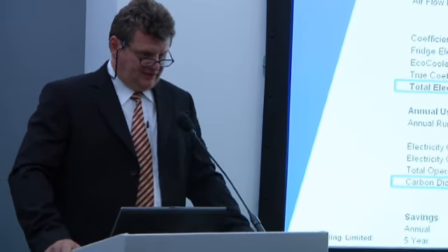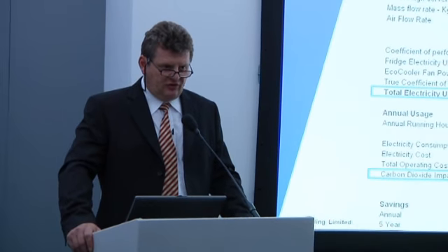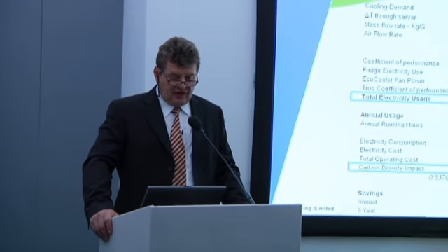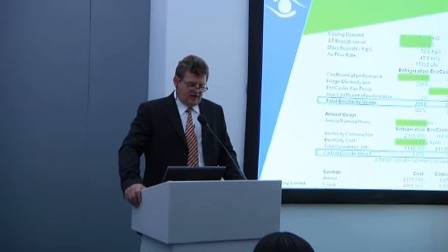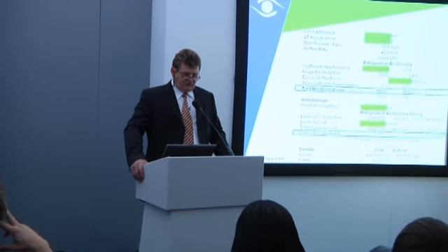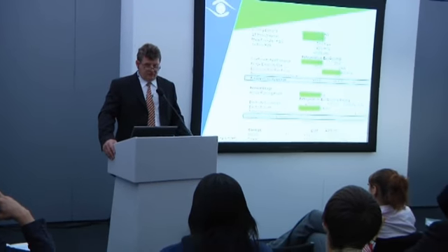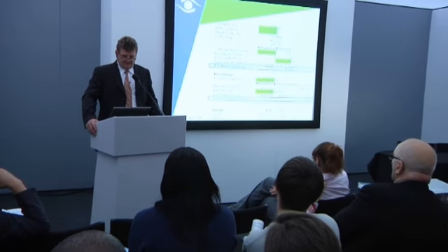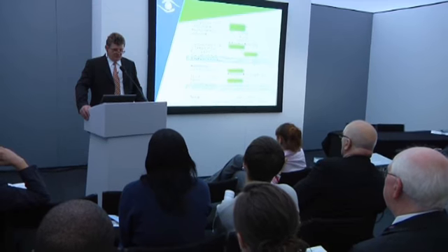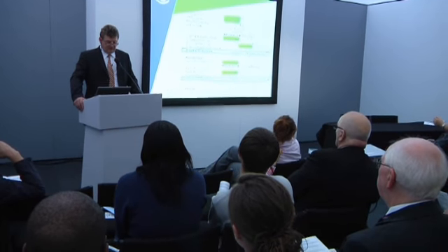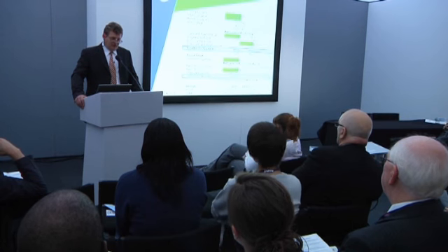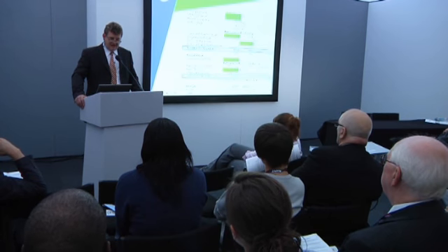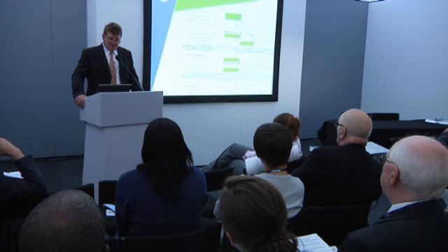When we look at a data center, a lot of people do get a little bit misled in that they concentrate a little bit too much on the actual cooling load. There's a little bit more to it than that. What we're actually trying to do is give all the servers the right volume of air. Wherever that air comes from is irrelevant, but you've got to give it the right volume. Now, 500 kilowatts of servers actually adds up to about 42 cubic meters per second of air. That's a lot of air.